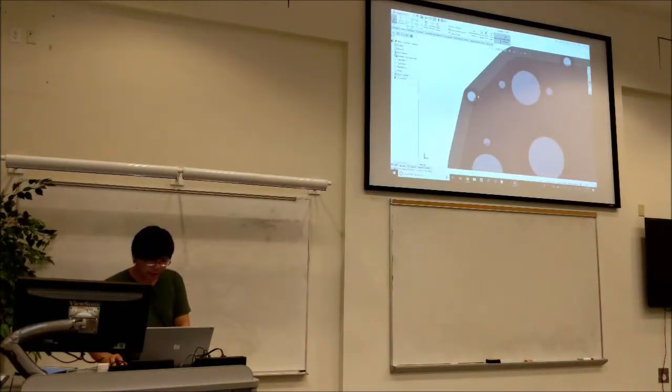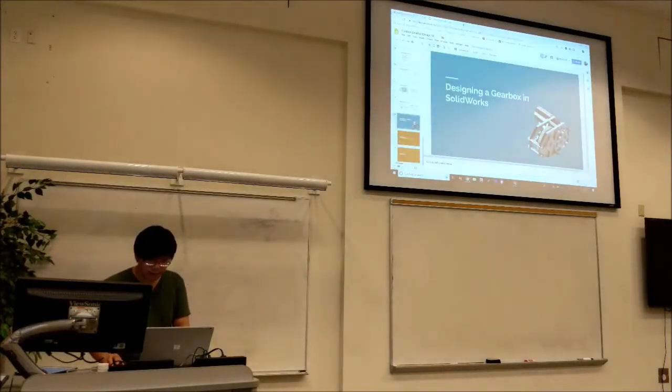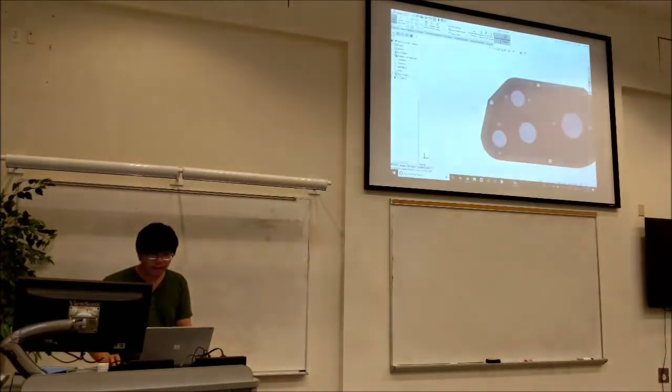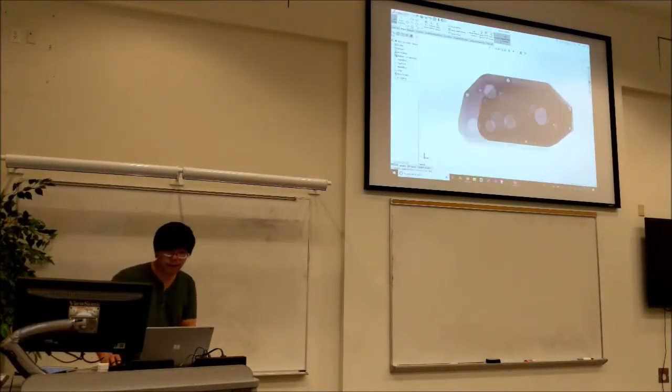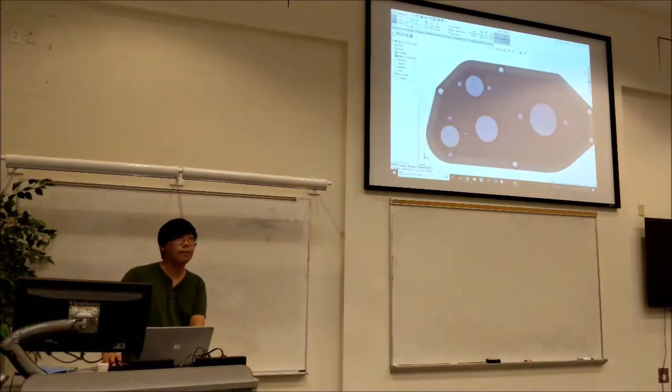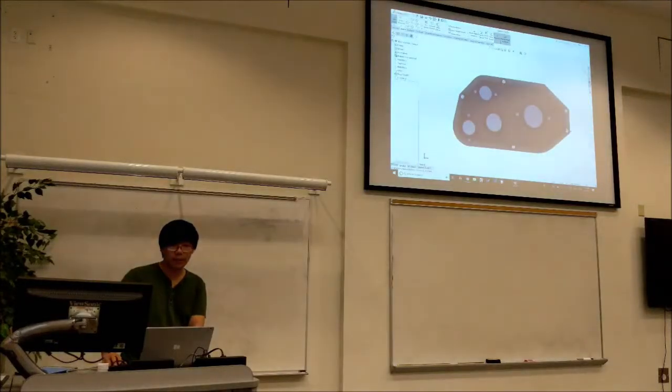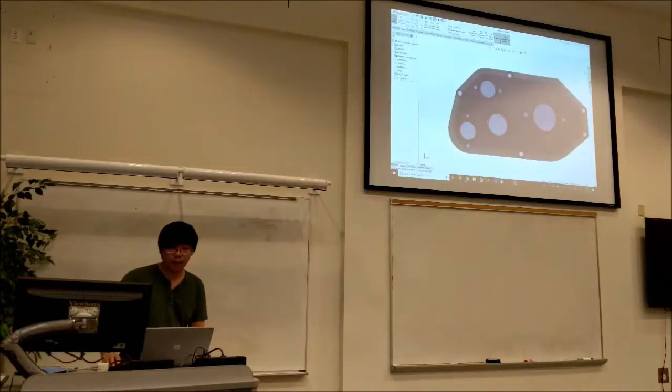If you notice here, we're going to keep this material, this outline, for this hole. That's similar to what we have here, where you can start to see how this is going to turn into the render. After we define all the holes, we're basically going to connect them up. We're just going to draw lines to all the holes, and then offset them. Once we do that, it'll form struts between all the bearing holes, and when we extrude through this material, it'll only leave what we need.